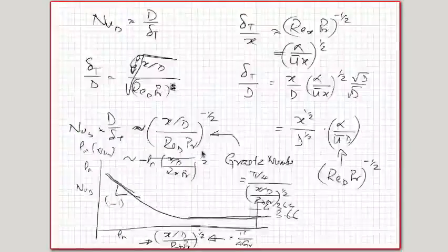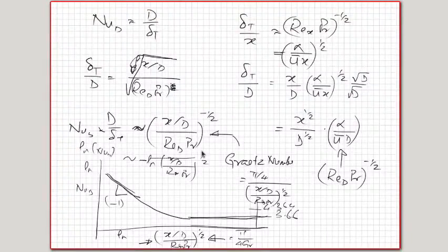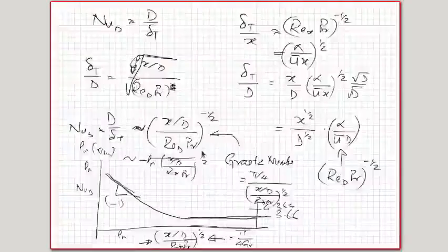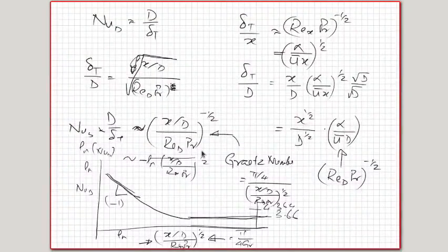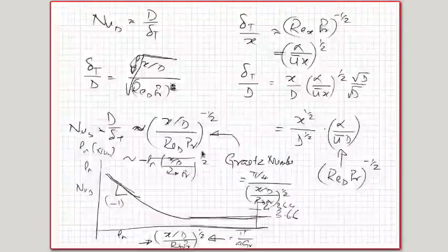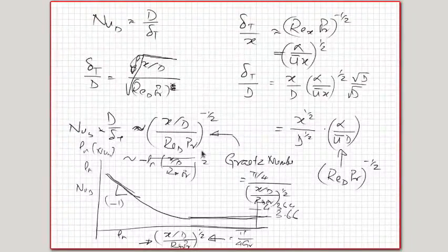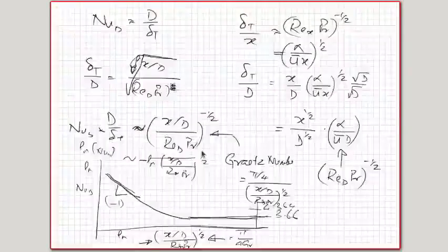Okay. So this is basically how you expect the thermally developing flow to behave with x. So with x, there is a decreasing Nusselt number. We all understand that at the inlet there is a singularity because there is a finite temperature difference across zero thickness of the boundary layer, and therefore the Nusselt number or the heat transfer coefficient is infinite.